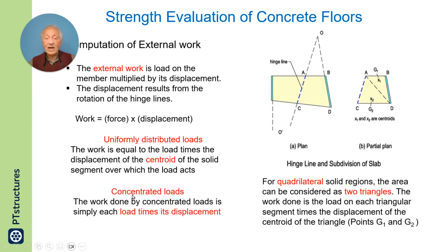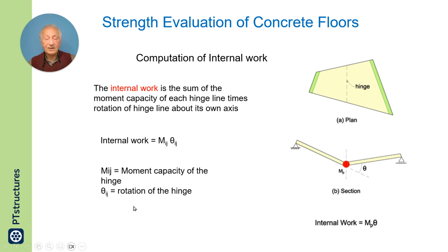Now, if you have concentrated loads, the work done by the concentrated load is the load times the displacement below the concentrated load. This has nothing to do with the centroid of the segment. It is displacement under the concentrated load.